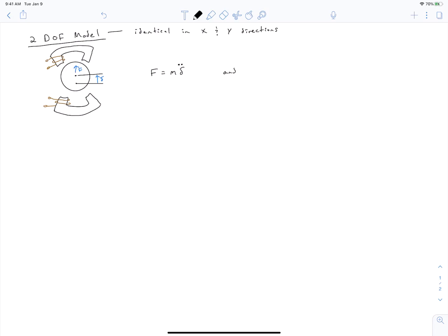And we're going to relate this back to our linearized force model for a magnetic bearing or a bearingless motor, which is that force is equal to our force current constant, Kf, times the current that's flowing, plus our force displacement constant, k delta, times the amount of displacement. And we've developed this model for both a magnetic bearing and a bearingless motor. Remember, for the bearingless motor case, we wrote it in a vector form like this. It doesn't matter whether you're talking about a bearingless motor or a magnetic bearing at this point. We're just talking about it along a single axis right now.